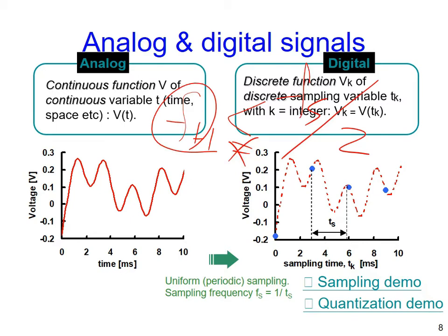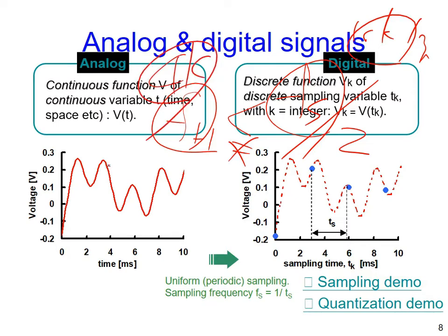So if you tell me right now my ADC operates at 10 kilohertz, how about your input signal frequency? The highest should be less than 5. Got it? And for our human voice, the highest for tenor, soprano, sorry, the highest pitch from the lady, okay, how much? So it means to record, to digitize our human voice, we need 8 kilohertz at least.